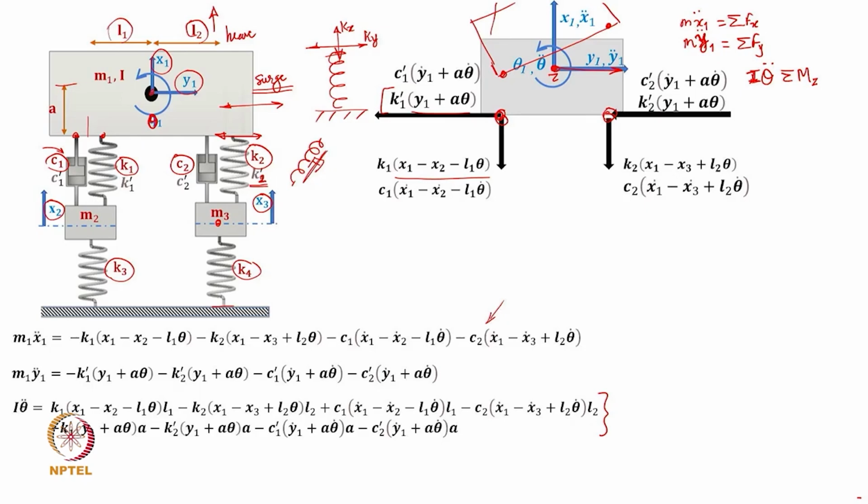So, all these forces are because of the vertical stiffness and vertical damping, which is K1 C1 and K2 C2 at the two connection points or at the two suspension locations. In addition, as we discussed, a suspension is physically shown like this, it not only has this vertical stiffness K, maybe if I can call this as Kx, but it will also resist any lateral motion. So, that resistance to this lateral motion is going to be quantified through Ky or the stiffness in the horizontal direction, which in this particular case has been defined as K1 dash and K2 dash.